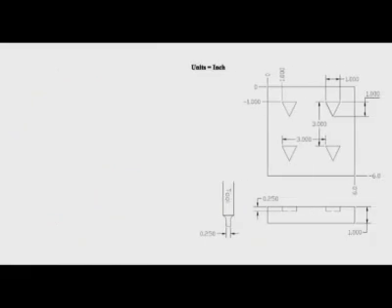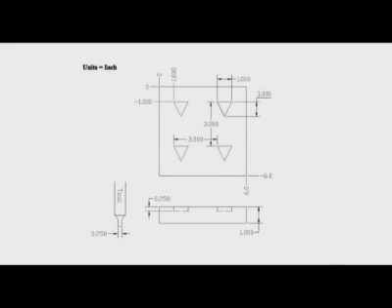In this programming example, we will make a profile pocket and apply a grid pattern to make multiples from the original. From our example part print, you will see that we have 4 profile pocket shapes. We will start by programming the profile pocket in the upper left corner and then apply a grid pattern command to make the remainder of the pockets.